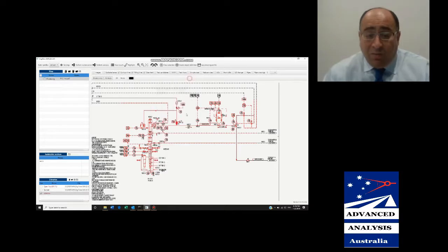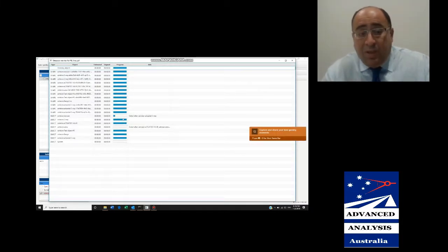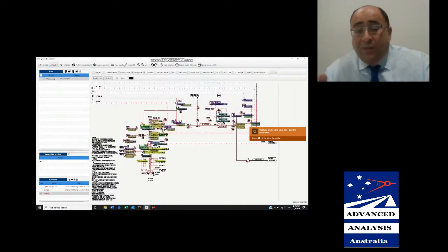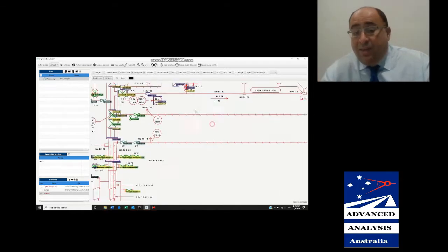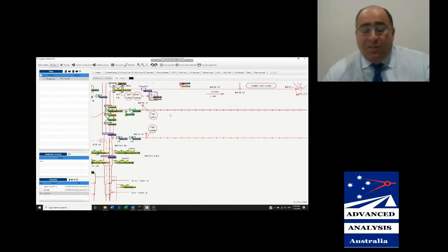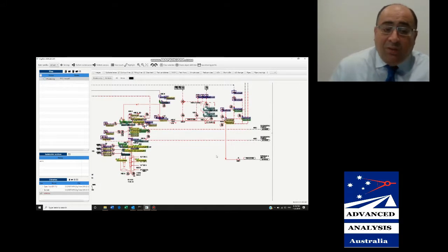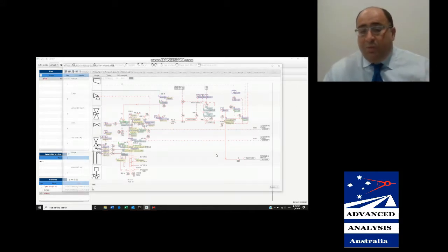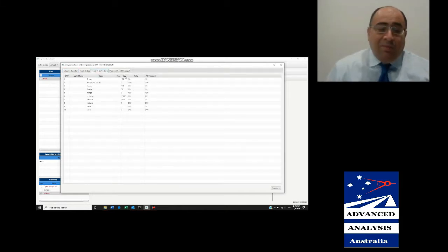A new variant of the software coming out soon called PFD to RBD can read in a PDF, a simple PDF of a process flow diagram, and output a reliability block diagram, an RBD, in XML format, which is directly importable by ReliaSoft's BlockSim. And this can carry out RAM analysis on these RBDs. So now you can carry out a RAM analysis without having to go through the laborious process of creating block after block, and it can be thousands.